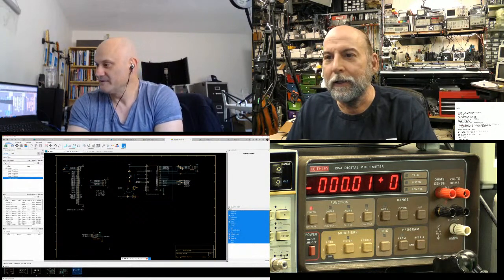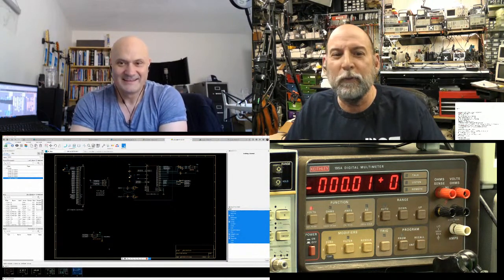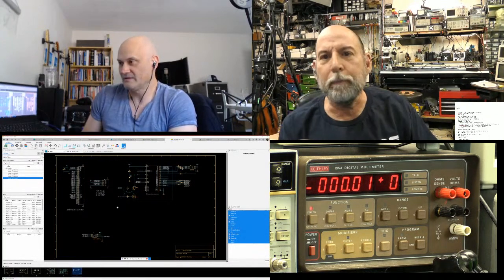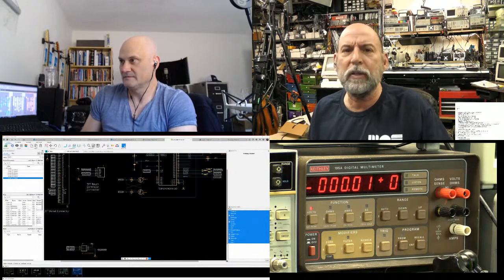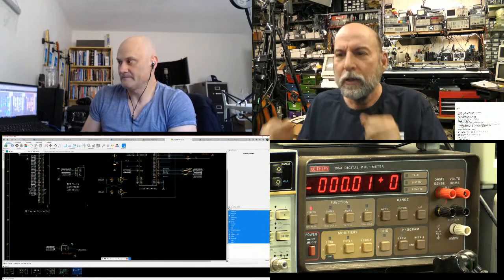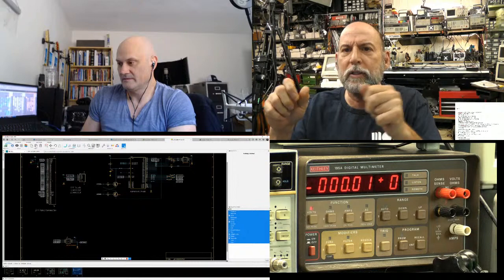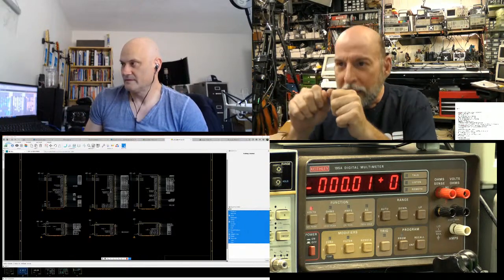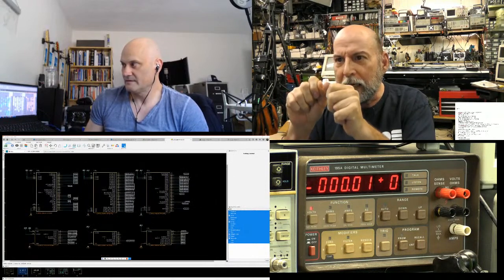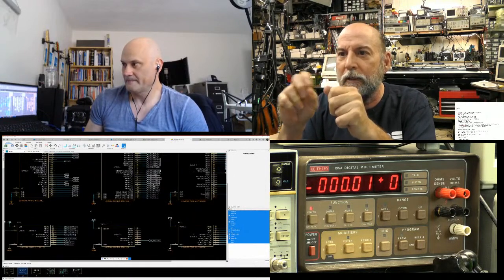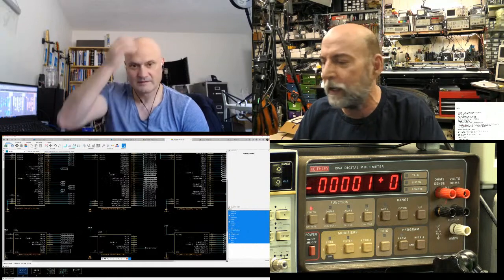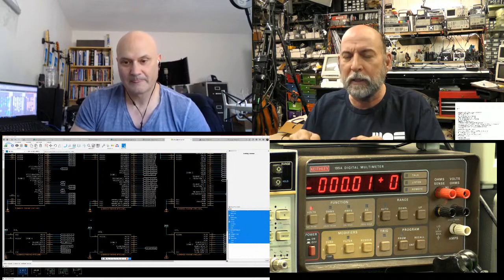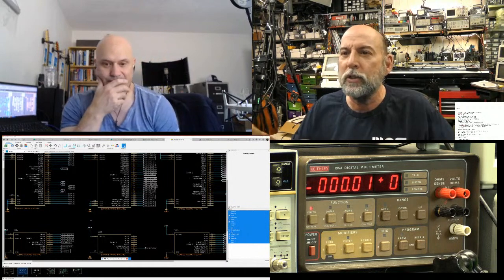Yeah. So interesting. I was going to say one quick story is, back when they did the VIC chip, they didn't have electrical rule checks that interface to the design rule checks. So they would hand check these chips. They would sit down at a big piece of Mylar with, I call it a ruler, they call it a scale, and they would actually measure the gates and the overlap of the gate to the channel and check their transistors against a schematic. And it was all hand checking. An engineer could be brilliant, but then he was expected to spend 3 months hand checking his chip.